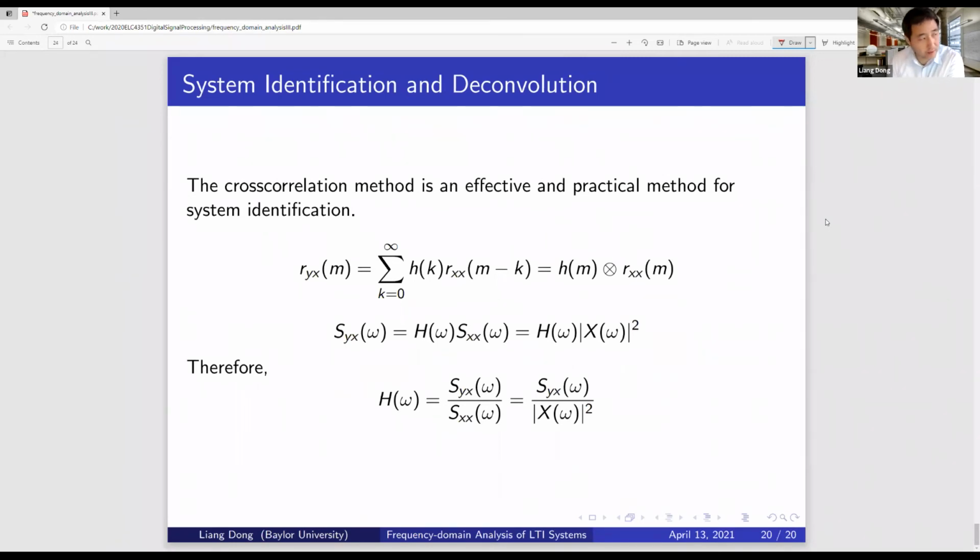In practice, we have some trouble getting h[n] as a deconvolution from y[n] and x[n]. First of all, deconvolution is complicated, and I have to do the iteration to do that. It's much nicer in the frequency domain or z domain, where we just use one shot of a division to calculate capital H, and then use the inverse Z transform or inverse Fourier transform to find little h[n].